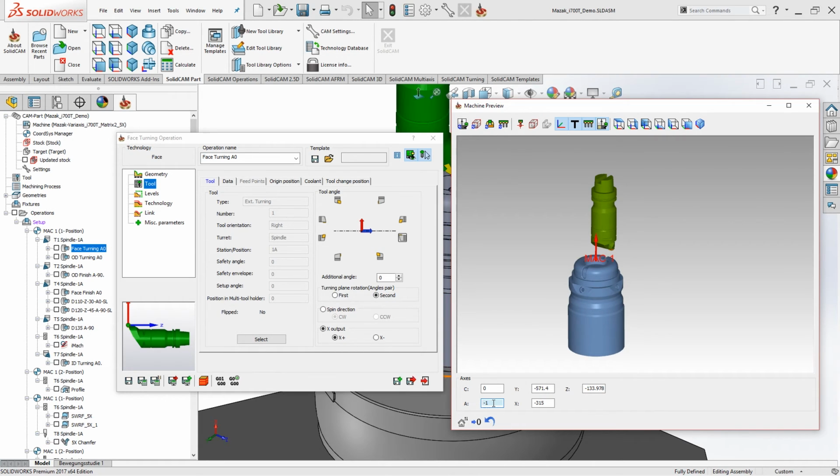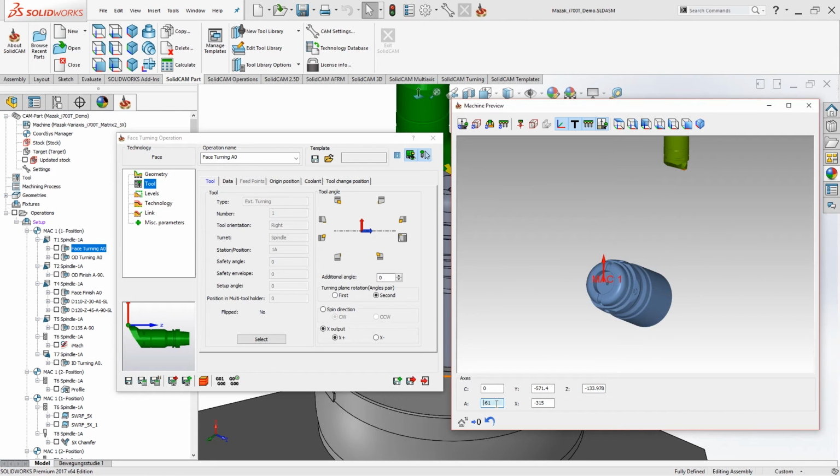If I try to move with my cursor in the negative direction, you will note that the coordinate system becomes red, which indicates that this is not possible, as we actually defined in our VMID. Therefore, I'll move our coordinate system over here, and I'll apply it to negative 90. As you can see, the coordinate system changed its position. You can also note that if I say 0, the coordinate system is rotated by 90 degrees. You can't see it now because we don't have any STLs. So let's try to do that now.